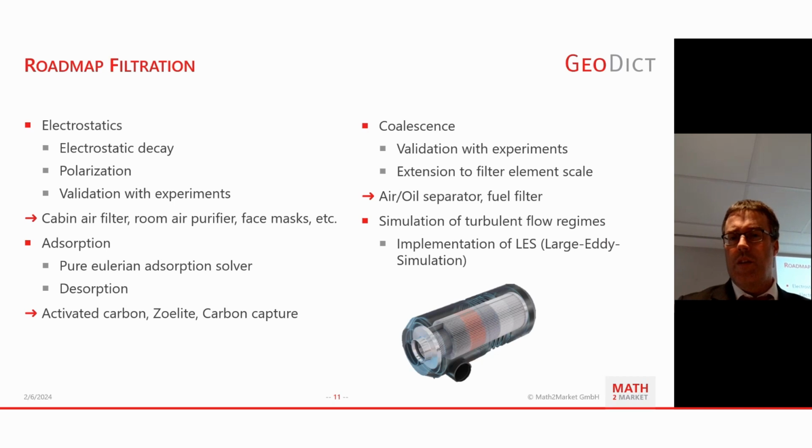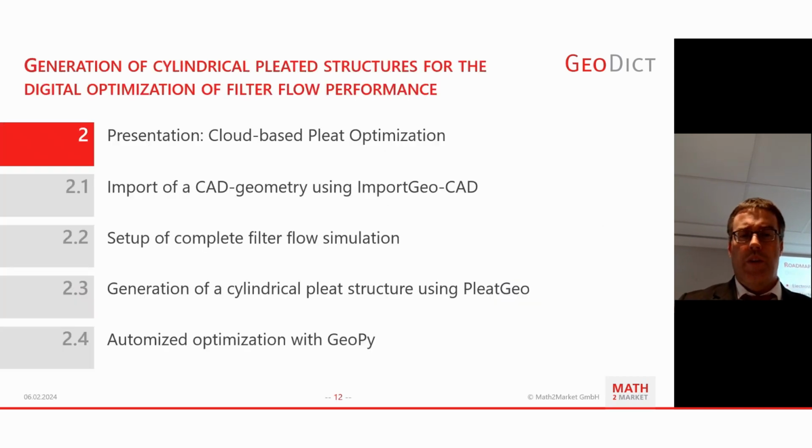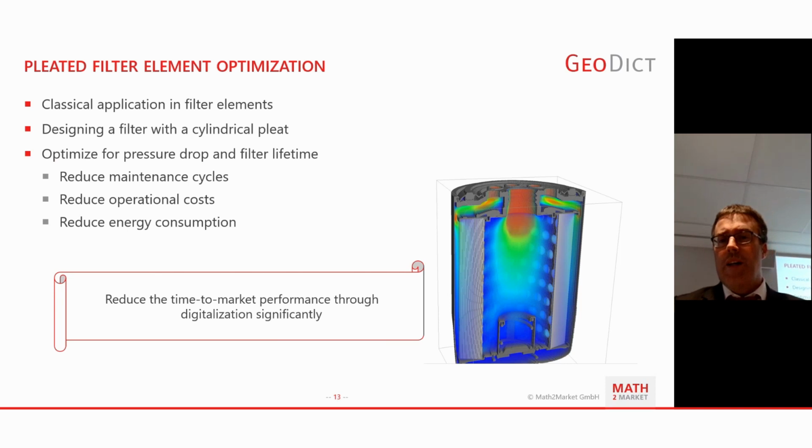We start with the workflow titled today, Cloud-Based Pleat Optimization. A classical application for this framework is the optimization of pleat count in the filter element. By running simulations with different pleat counts, it's possible to digitally find the optimum between the pleat count, or the filter area, and the pressure drop.